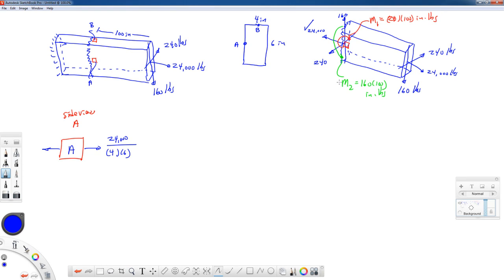If you bring in a short ruler to your quiz or something, you can bend it. That ruler would be in tension if you put this kind of force on it in the back at this point A. Tension on the top. Does not cause any stress at point A, however. Let's draw the cross-section and let's see how that is the case.